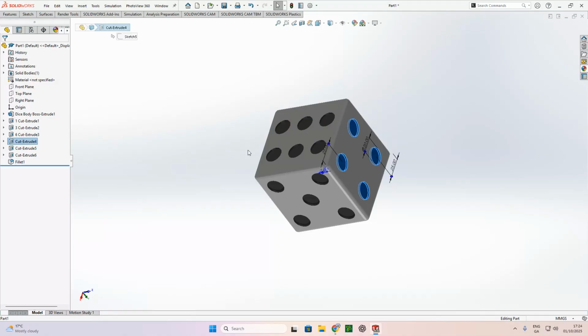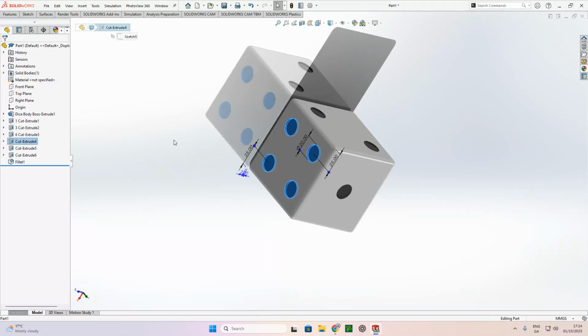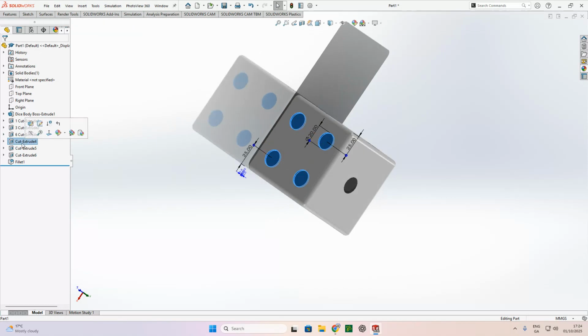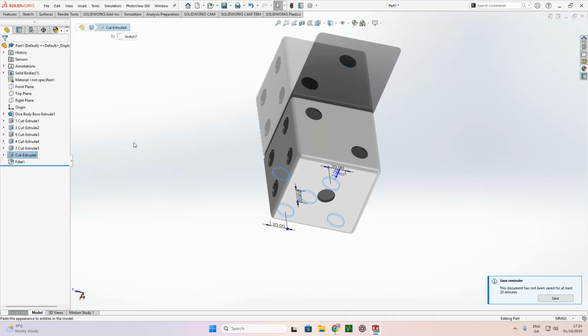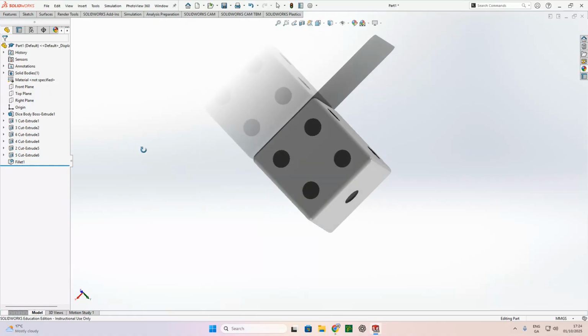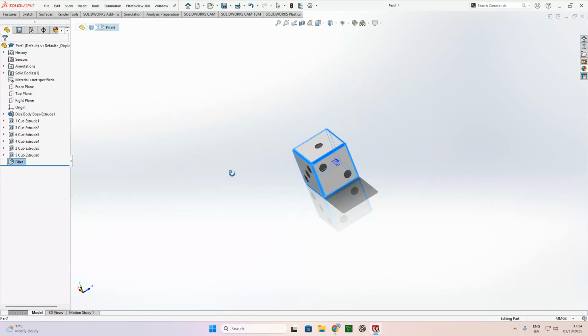What's the next one? So when I click it here, it's showing me, so that's number 4. So click it, press F2, 4, space, number 2, click it, press F2, number 2 then, and finally this one is number 5, last one, F2, 5, and I renamed it. Okay, and fillets don't need to be renamed, but there we go.